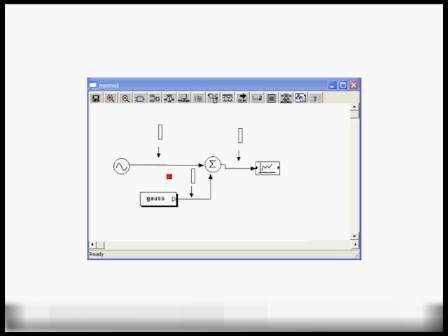And if for one reason or the other the sine wave wants to generate more samples and the buffer is full, then another 128 more cells are added to the first in first out buffer. We'll describe those later. But in general, what happens is that the 128 samples that the sine wave generates matches the 128 samples or cells which the FIFO is created with, and the add block would consume all those samples